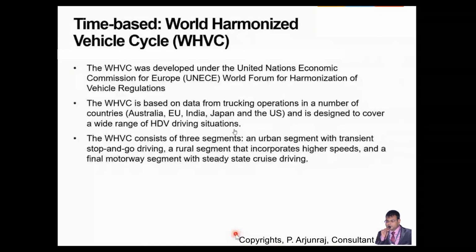And again, this is the way different kilometers, what I was telling, 10,000, 40,000 or 1 lakh, these different kilometers are for a complete vehicle. And there are some design verification plans that we normally do that will also be specific for a particular component alone. Say for example, the brake system or a steering system or a suspension system or a frame.